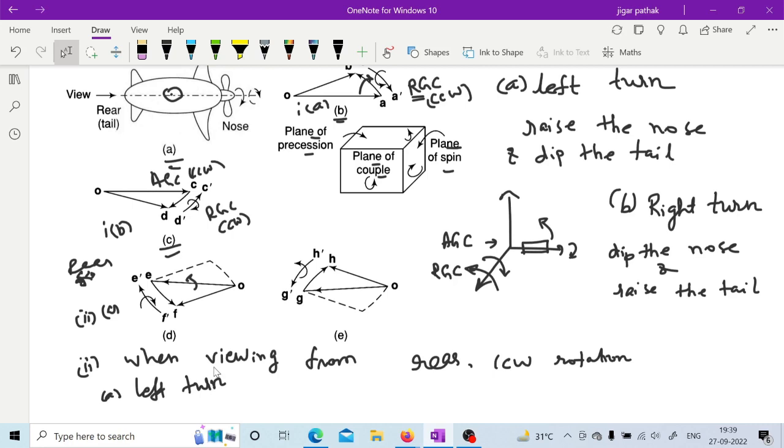So what is going to happen in this case? Can you see what is happening here? Anyone? Nose rise, nose and tail dip? Nose down and tail rise. Yes, the same thing will happen, because whatever active gyroscopic couple is generated here is in counterclockwise direction.